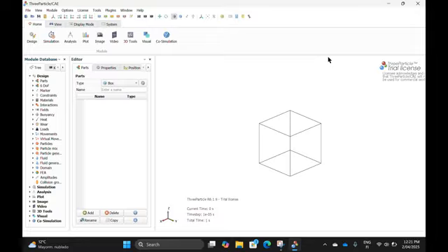At some point, 0.5 exactly, there is the cylinder lifting, suddenly appearing. You see that? But it's not there yet. What I do is I define everything at the beginning. Define a lifting here. Say the lifting should start at 0.5 and end at 1.5. That's the idea. So I define more or less everything at the beginning.